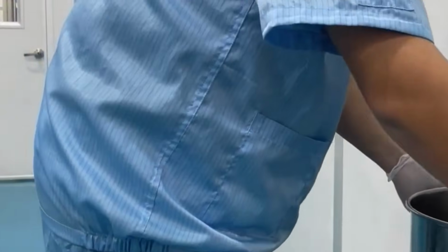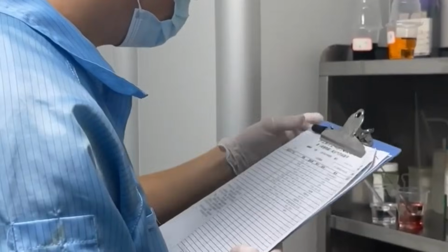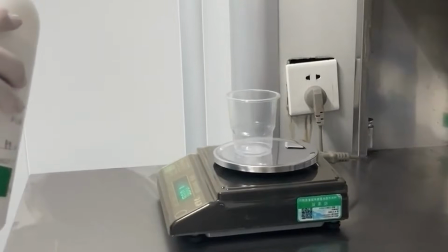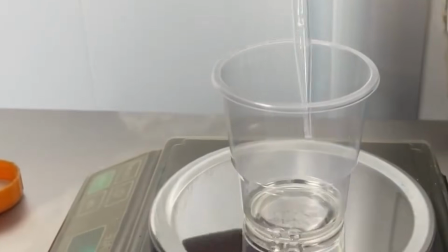Each pallet is stretch wrapped using rotary arm or turntable systems. Stretch film is applied with controlled tension and overlap to stabilize the load. Barcode labels are applied to two adjacent sides for warehouse scanning.